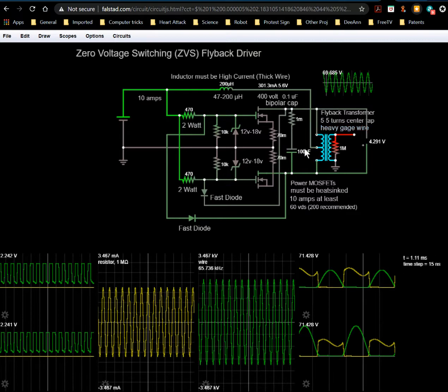But at any rate, if you had some short circuit, like through a diode, it'll actually be able to maintain that current. But since it's through a real-world diode with real-world circuit resistance, it eventually dissipates all the energy in that field, so you can't keep it permanently stored like you can in a capacitor. If you had an ideal capacitor with no leakage resistance, you could store that energy in it indefinitely. Weeks or months, and even in a real capacitor you can store it for hours in a big electrolytic, and sometimes days in other more efficient capacitors.